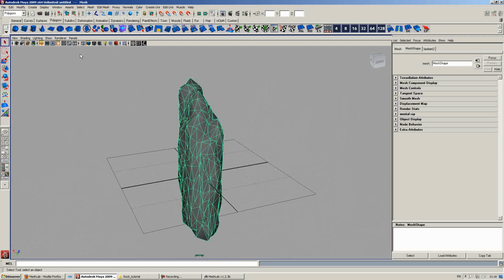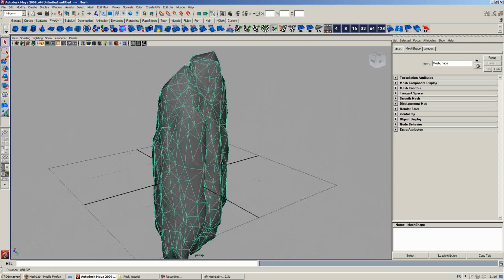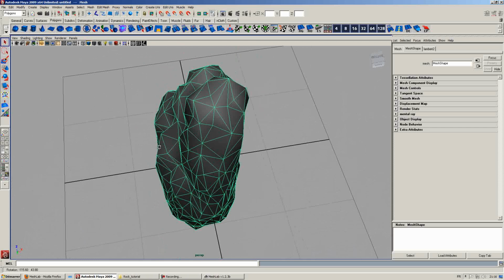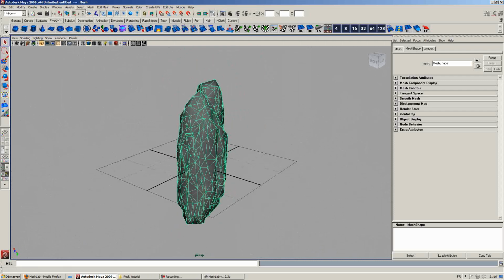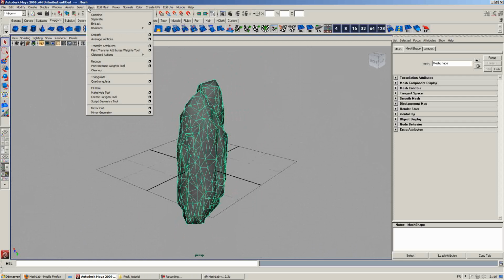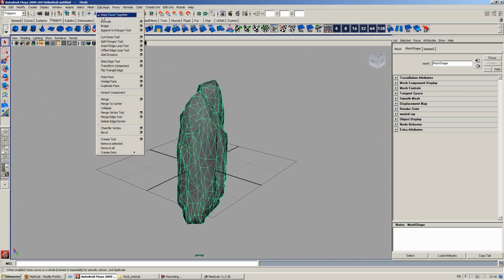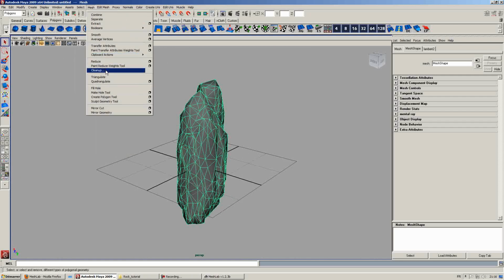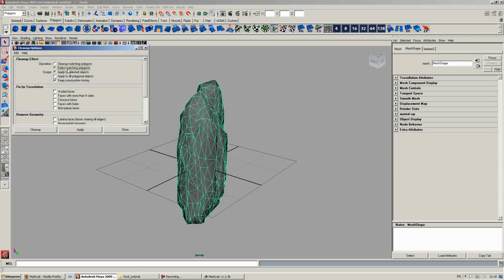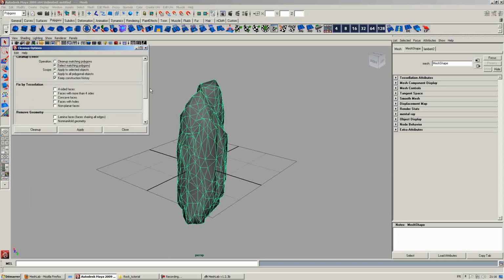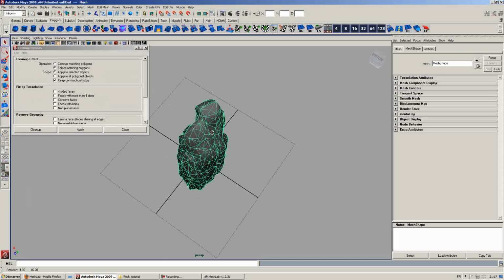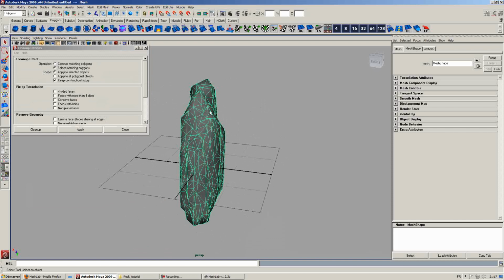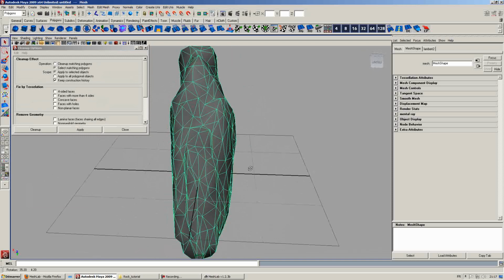That way we can make sure that the mesh doesn't have any problem or non-manifold geometry in it, just in case. So in Maya, in order to do that, you just go to the Mesh menu and click on Cleanup. I'm using the default options. Instead of clean matching polygons, I do select matching polygons. That way you can manually examine which part is problematic on your mesh.